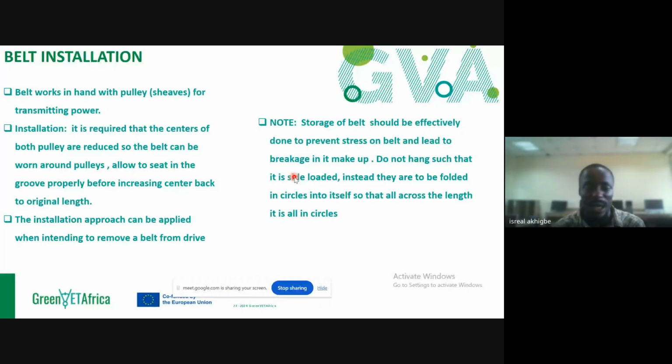Output rotation. Now, that thing that's going to give us rotation, whether we like it or not, from physics, there's something called centripetal and centrifugal force. Now, that force, if the driver is not balanced properly, is not mounted properly, when it's in operation, that centrifugal and centripetal force will cause that thing to vibrate and move your driver from one point away from the desired point.